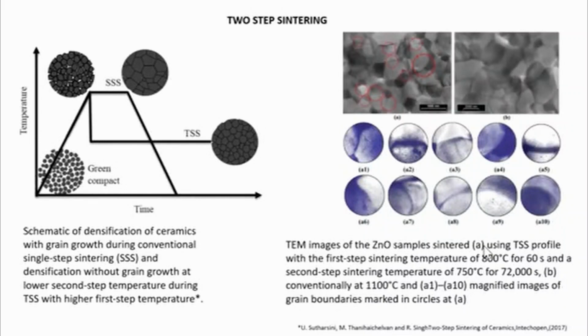Ten different grain boundary zones were analyzed by the investigators using TEM images. As they report, the triple junction seems to have pinned the boundaries of growing grains, and the curvature of these boundaries resulted from the mentioned immobilized triple point. However, no similar zones are observed in the TEM images from conventionally sintered samples.